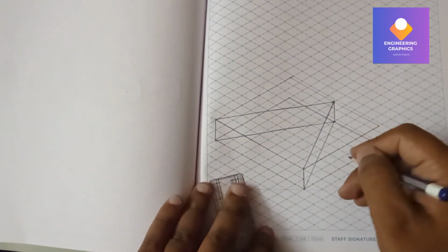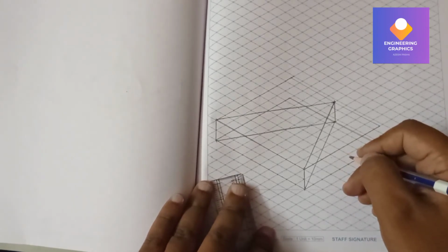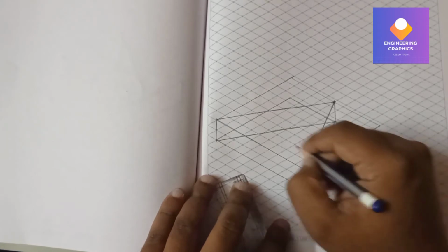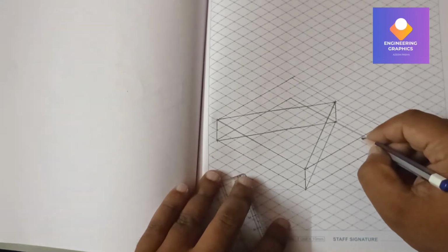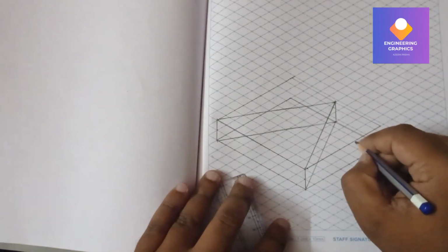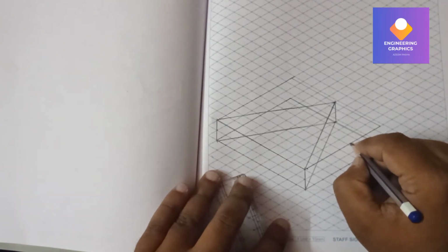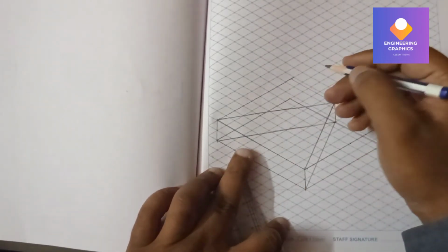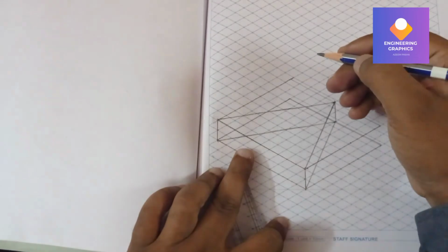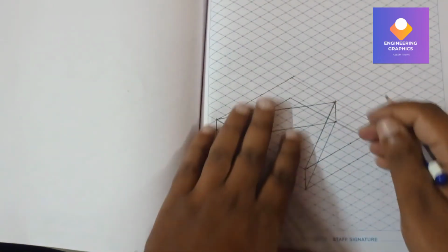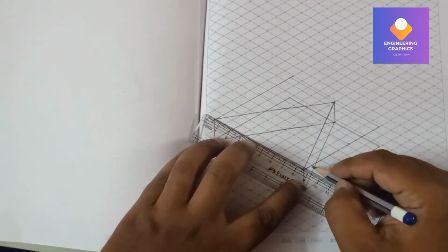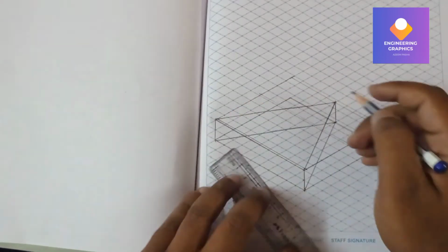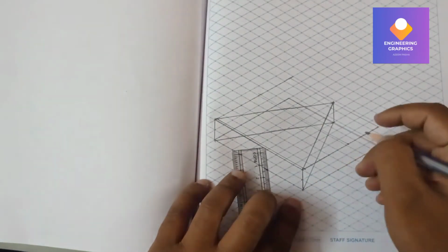Now we have to subtract the dimensions as we have measured in the top view of it. So on this side we need to mark 3 mm distance and on this side we need to mark exactly 32 mm. You can count it approximately, 32 mm you have to mark, on both sides. You can draw two lines joining these for 32 mm from the farther side, and on the nearest side we have to mark 3 mm as we marked. We have to draw two lines, and here exactly 2.5 marks.